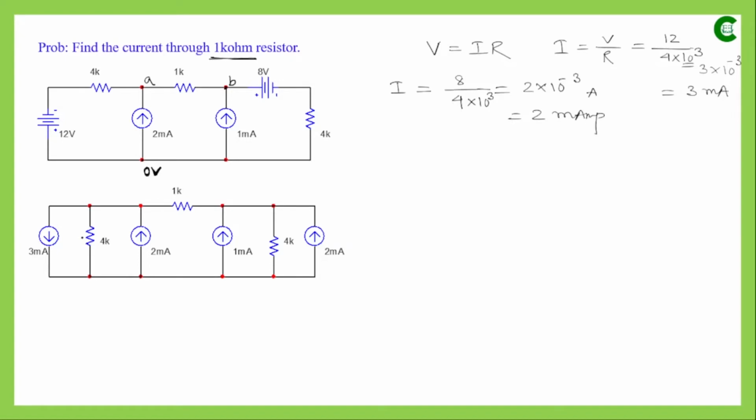So here in this transformed circuit, we now have this current source in place of this voltage source. Polarity wise, this is the positive terminal and this is the negative terminal of the voltage source, and as we know, the current will leave the positive terminal of that voltage source. The direction of the current will be downwards, so that's why the direction of the current source is downwards, with 3 milliampere that we have already got from Ohm's law. And as I said, this 4 kilo ohm resistor will be connected in parallel with the transformed current source. That's how it is connected now.